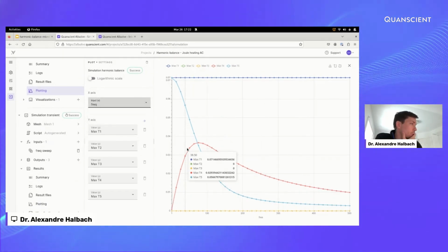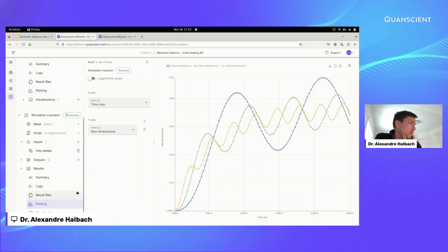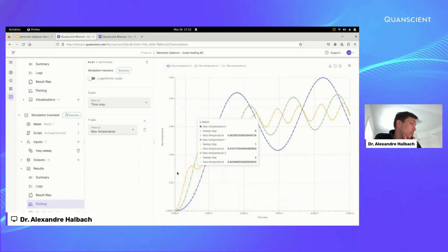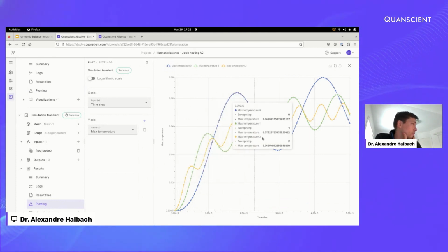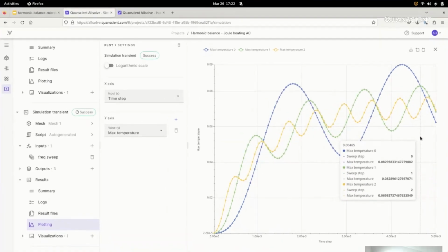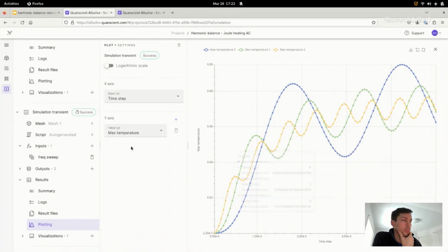And one other thing to notice is that it's 0 on harmonic 2 and 3, and on the harmonic 4 and 5, which is double the driving frequency, this is where you have actually the swing. And this you can see here. Here I'm just driving one period of AC current, and you can see that you have 2 oscillations for the heating. So obviously it's double the frequency, the swing around the static heating.